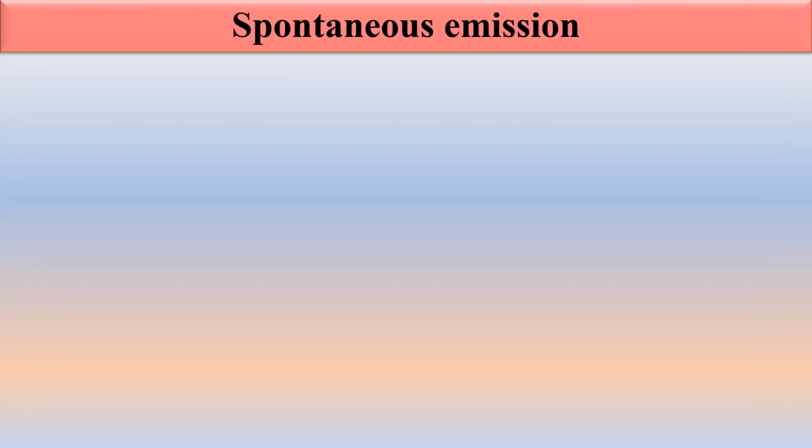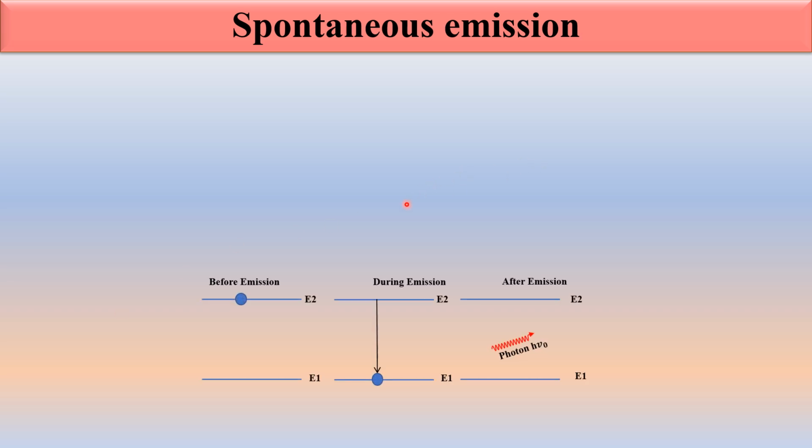Before understanding how the EDFA works, its construction and its architecture, we just need to know some basic terminology, which is spontaneous emission, stimulated emission, and population inversion. I have made a separate video on all of these, but let's see them in short. What is spontaneous emission? When light automatically moves from a higher energy state, or you can say the metastable state, to the lower energy state without the effect of any incoming photons or incoming optical signals, this is called spontaneous emission. And during spontaneous emission, when the photon is emitted, that photon is very random with respect to the incoming photon signals.